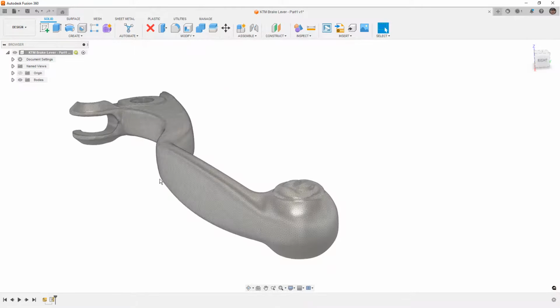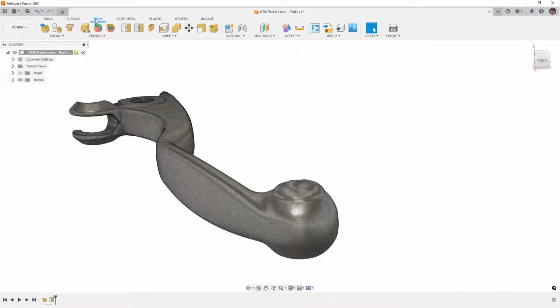To understand whether or not that is appropriate, let's first get into mesh section sketches. Now, mesh section sketches are a way in which we can gather data off of the scan. It doesn't have to be a scan, it can be just a mesh file that you bring in. But this is the main way in which we are going to get information off of this. So to get started, we want to go to our mesh tools and select Create Mesh Section.